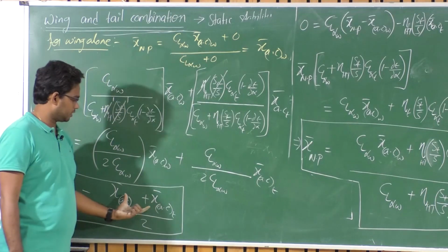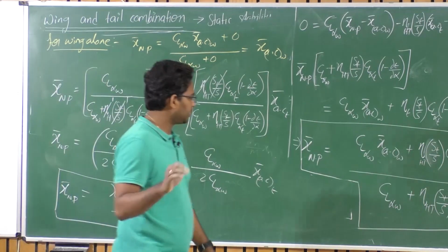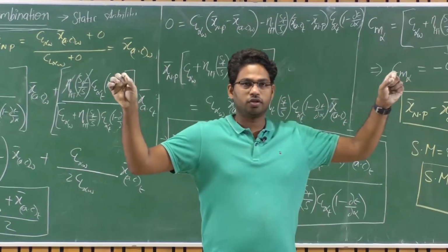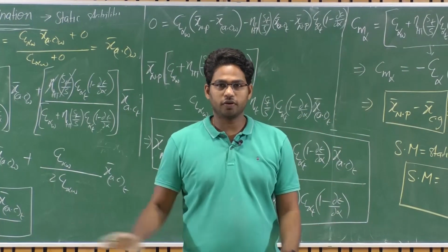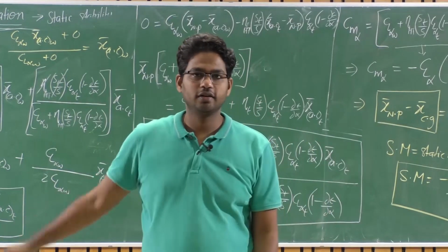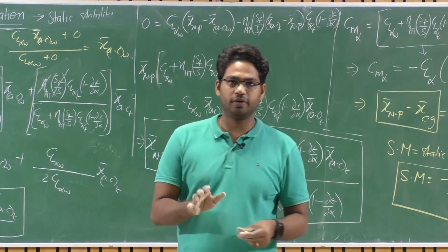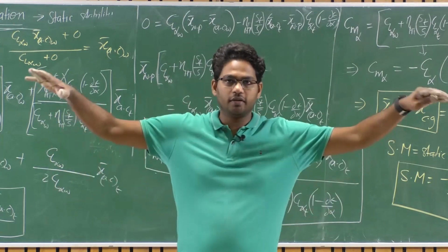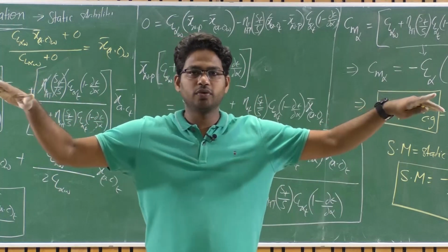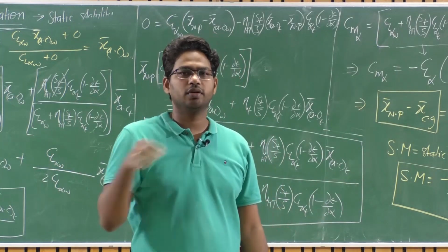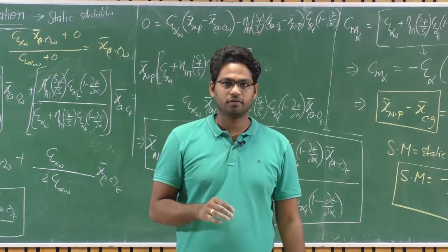Do you appreciate that? So in that case, it is nothing but the midpoint of the distance separating these two wings. If you don't accept this result, we'll try to demonstrate it. So in the next lecture, we'll have a demonstration of two identical wings, and I'll prove that the neutral point is midway between their aerodynamic centers. Okay? Thank you.